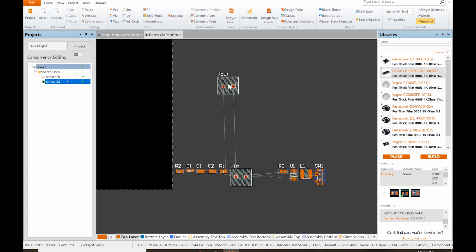So whenever you make a component, always make sure that your center is the center of the component, because when I go to rotate it, it rotates around the center. There are some components that rotate wildly around a very large axis. So I would go back and edit this component and make sure that the center is the center of the component, but I'm not going to do that now.